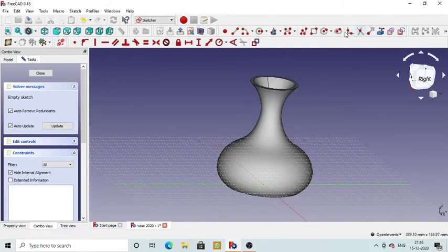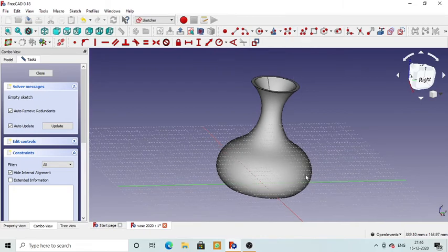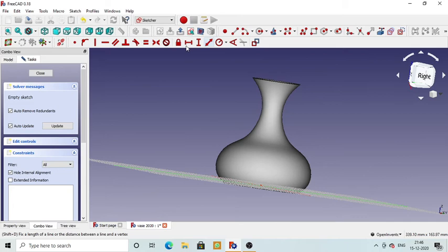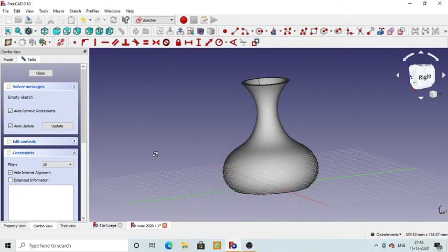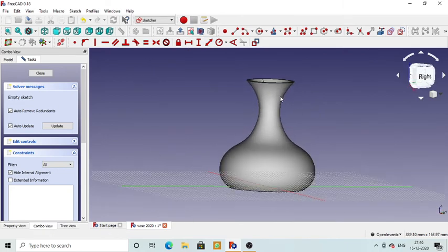First of all, select this, create a polyline, then make it in the horizontal, vertical, and this is a small one. Then after that you are supposed to select this B spline curve, 1, 2, 3, and then 4, and then join these 2 points by using the coincident constraint. So these constraints you are supposed to use very wisely. After that, points will be created, adjust it, and then you will get a pretty looking curve like structure.